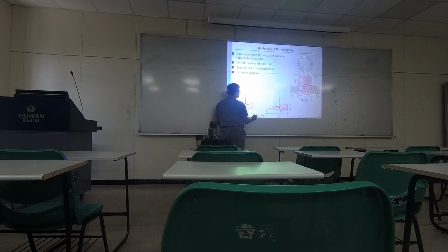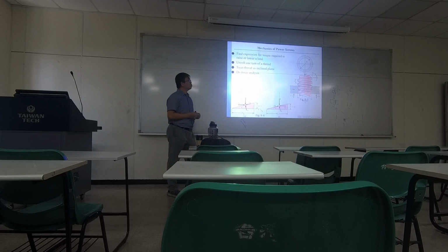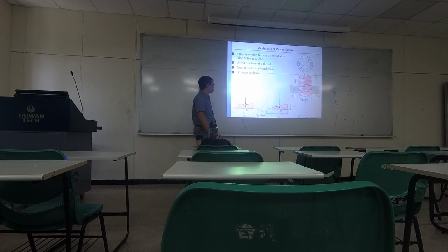This would be your pitch, because as you go uphill following this helical curve, your movement up would be one pitch. So then you know what this geometry is going to look like. Let's say all the forces are concentrated at one particular point. Then you can analyze what the reactive forces would be.